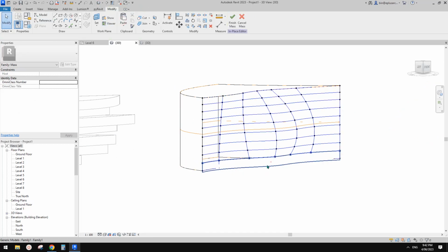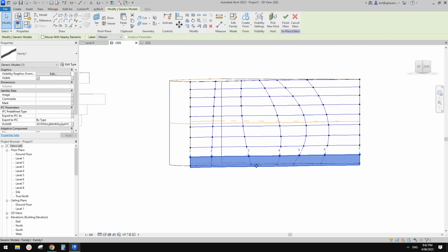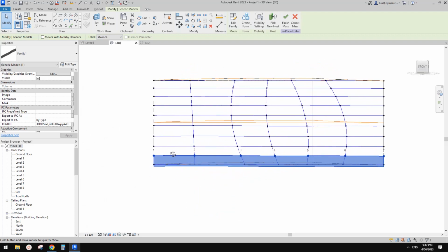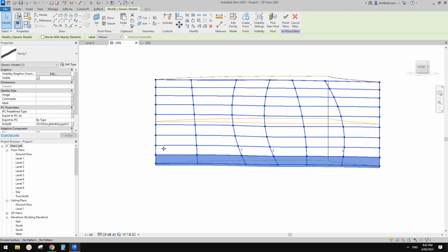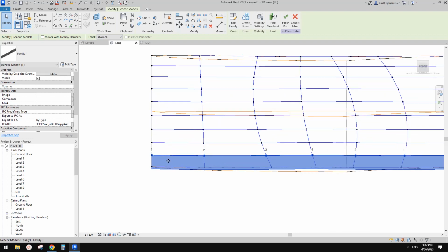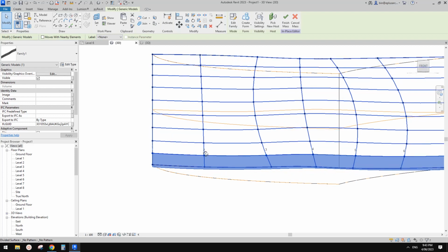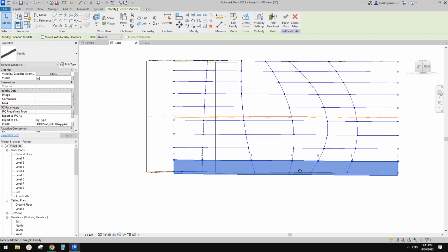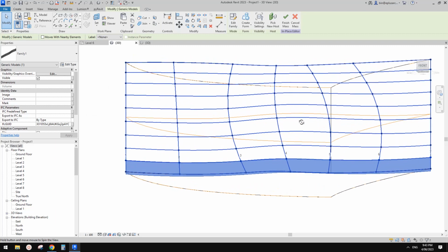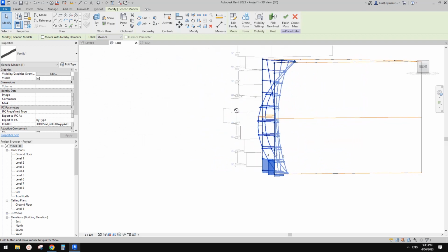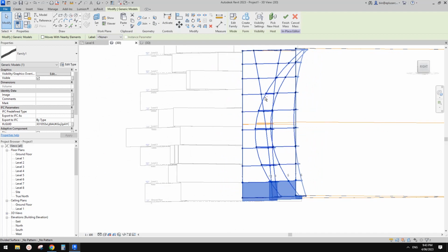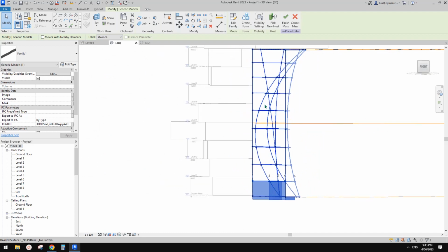Oh, hang on, it's already there, but you can see the orientation is not right. It's going the other way. It's supposed to be 4 meters. I think the issue we are having here is that when Revit calculates the grid, sometimes it uses the direction between this point and this point, which means when I say 4 meters, it's not measuring from vertical 4 meters.